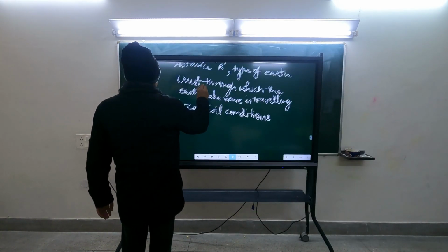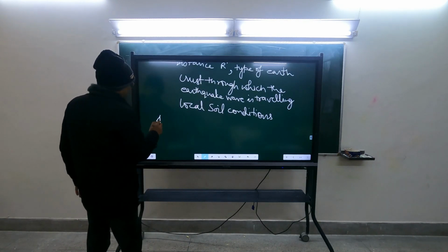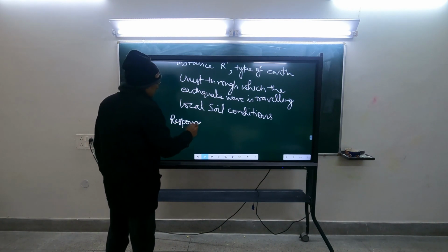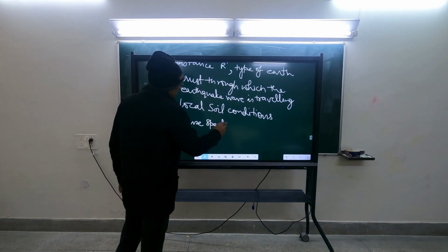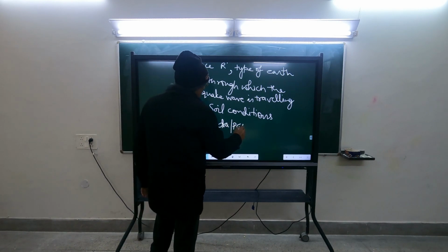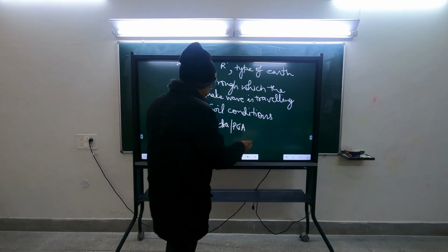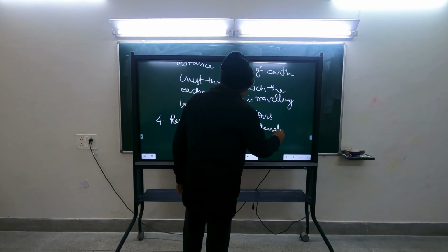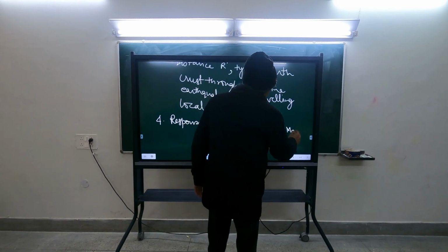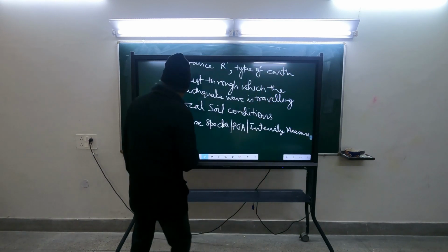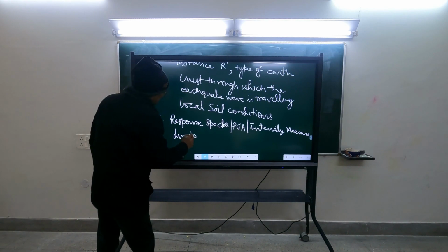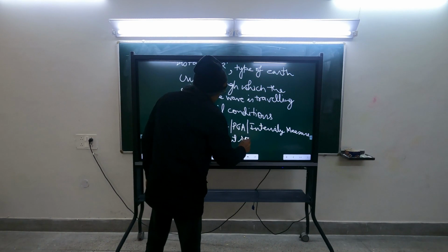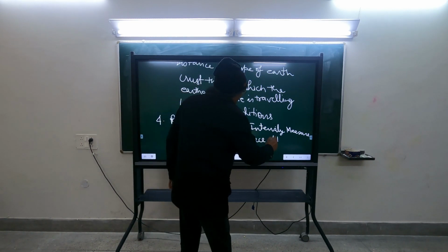Then you determine response spectra or PGA or any other intensity measure in which you are interested, due to different sources at the site.